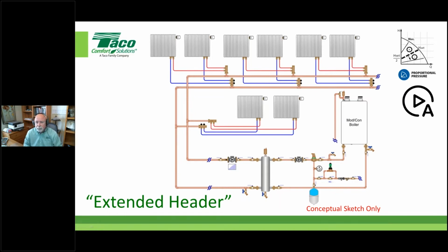We've got a specific boiler circulator that's feeding into a low loss header or hydraulic separator of sorts. And then the system circulator has the ability to vary its speed based on several things. In this case, we are showing TRVs, or thermostatic radiator valves. Okay, this extends out and covers a bunch more stuff. But notice you've got the mains, you've got the branches, and in this case, you even got twigs that impart resistance to this circulator. And that's got to be part of the calculation.